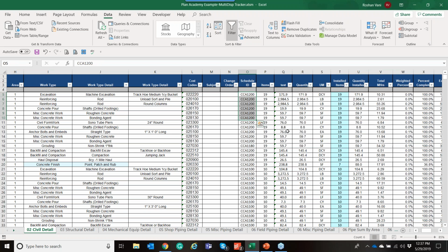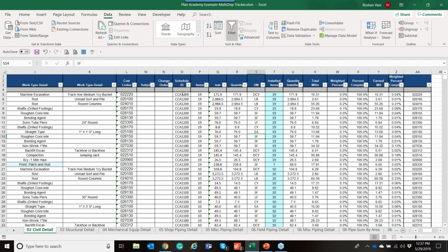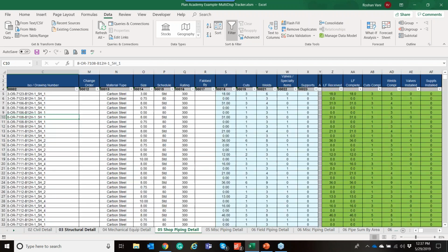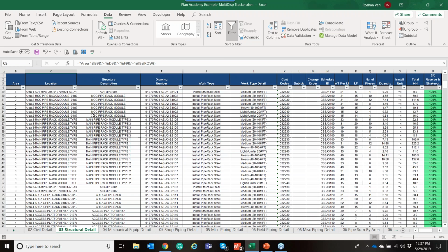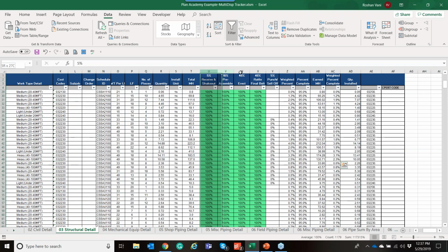What we oftentimes see in industrial construction is the Primavera schedule stops at a level 3, or what I call a level 3.5. And the level 4, level 5 tracking mechanisms are oftentimes done in a third-party system. In this example, it's Excel. Each of the different disciplines has its own widget-based tracker. All of the details that the job and the takeoffs that were done early on for the project are listed as row items here. And then we're implementing rules of credit based or milestone equivalent units for those different tasks.